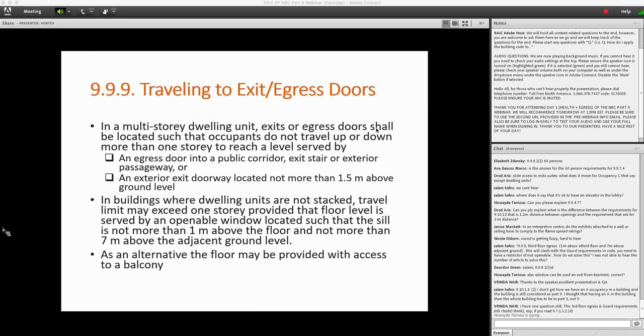So back again, that is under sentence 9.10.14.4, openings in exposing building faces, where it tells you that unprotected openings can actually conform to either the table in Part 9 of the code or to subsection 3.2.3 of the code.